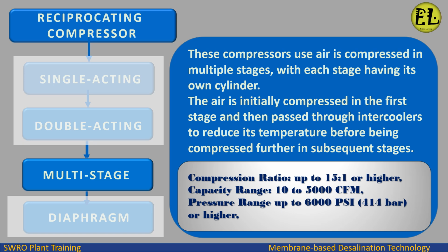Reciprocating compressor divided into multi-stage. In these compressors air is compressed in multiple stages, with each stage having its own cylinder. The air is initially compressed in the first stage and then passed through intercoolers to reduce its temperature before being compressed further in subsequent stages.